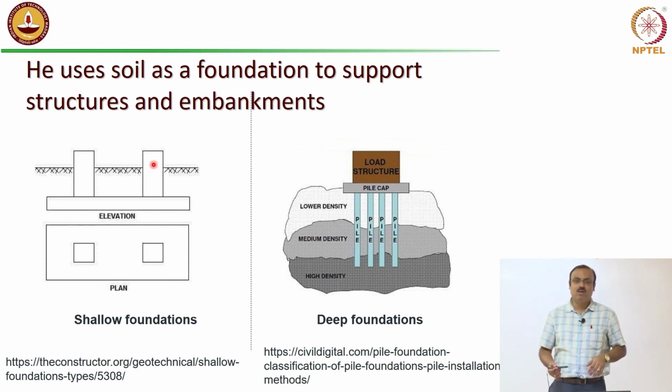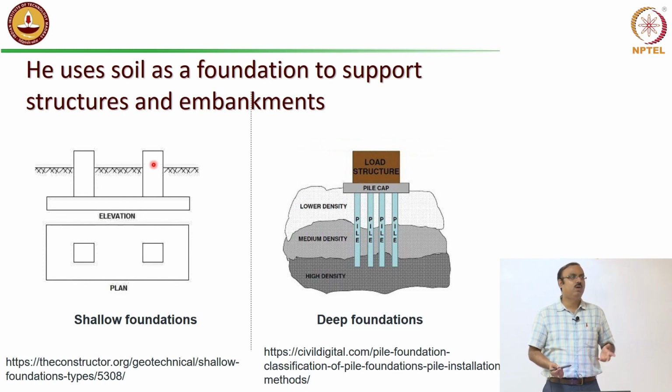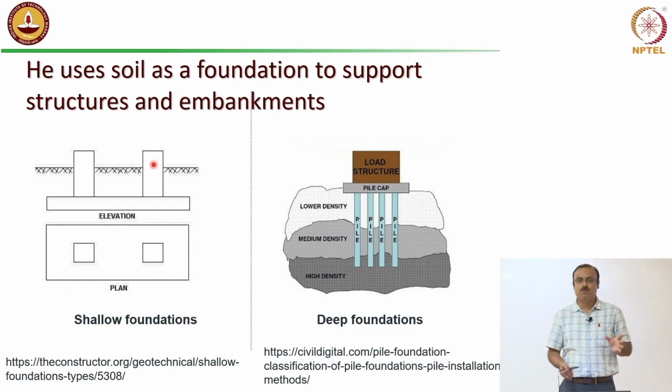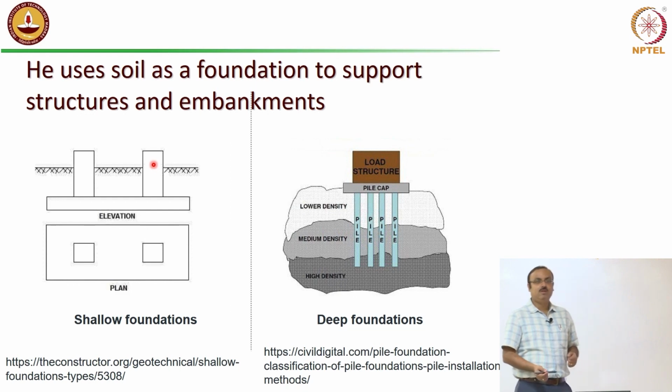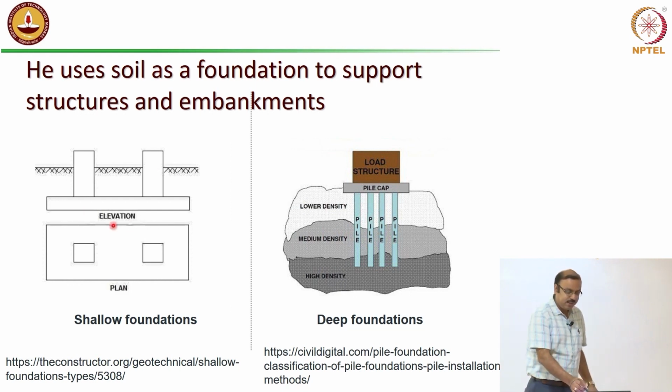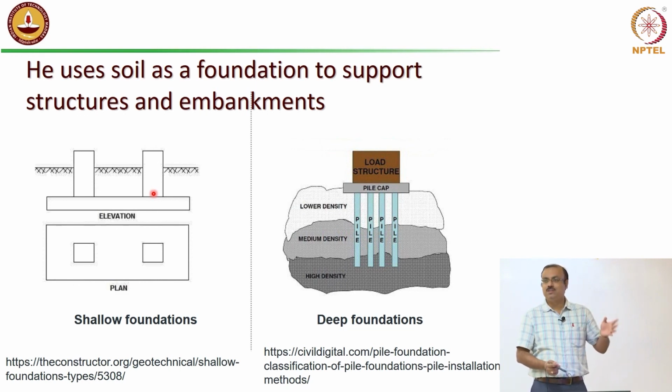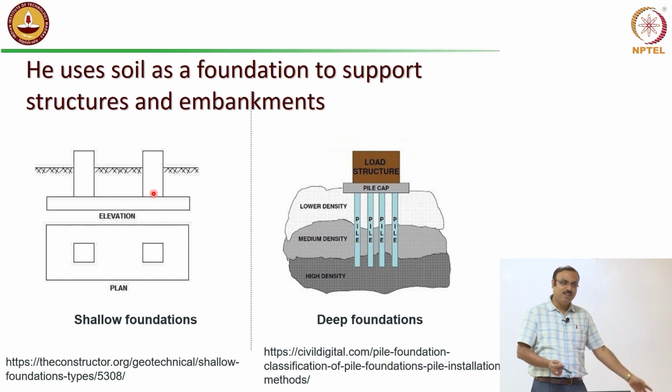Do you think that in a building or a bridge which is settling, you will be very comfortable to stay? No, right? So, one of the major serviceability requirements for any structure is that the settlement has to be within a certain nominal zone. There are codes for it, specifying how much settlement is allowed, but generally you do not feel comfortable if something is settling every day, is it not? Now, in those kinds of situations, what do you have to do? The foundation, by sinking itself, gave you a hint. It is not that the soil is bad. There is a soil slightly below that area which can take that load.